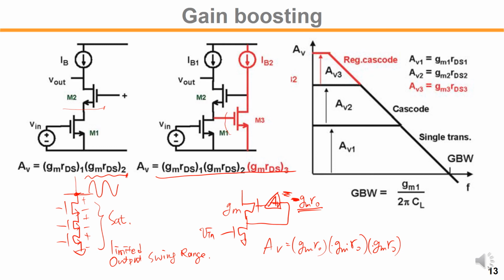Here on the right hand side, the red circuit is a negative gain amplifier, a common source amplifier. So this will bring up the DC gain like this in the frequency response. As you can see, this doesn't change omega u. So GBW doesn't change, omega u doesn't change, fu here doesn't change. It only boosts the low frequency DC gain, right? So if you require such high gain, then you may go for this technique.